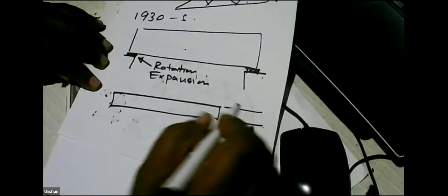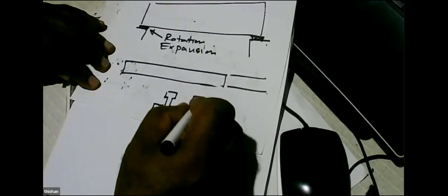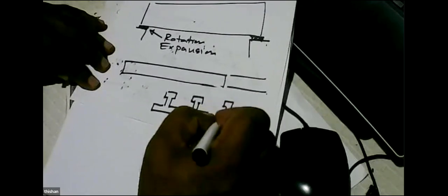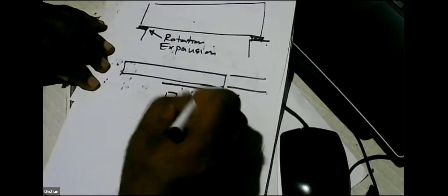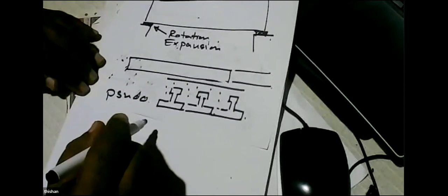And then they thought, okay, let's go for beam bridges, thin slabs, which are converted to bridges by placing the beams like this, precast beams. And then you put concrete, so you get a pseudo slab. It looks like a slab. They did this first in the coal countries. They thought, okay, concrete bridges also need bearings. So you get an expansion joint, a premix layer, and when you pass this joint, you can hear a sound from the tires of the vehicle.